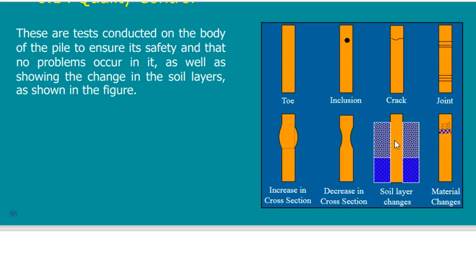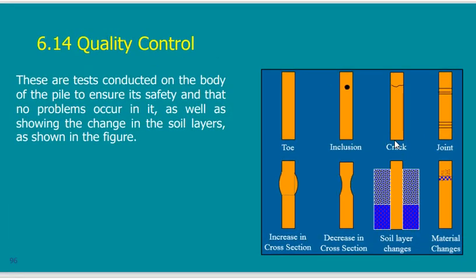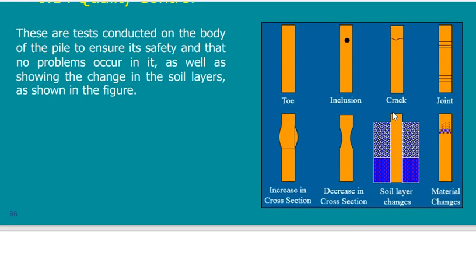So you can do this test on site, and you can do it on all the piles, so you will be sure of the depth, cross section, material, cracks, anything that is inside the pile, so we can check. So now we can check the load of the pile by testing, and the shape and the dimensions and the material of the pile. So now I can be sure of the pile in every way.